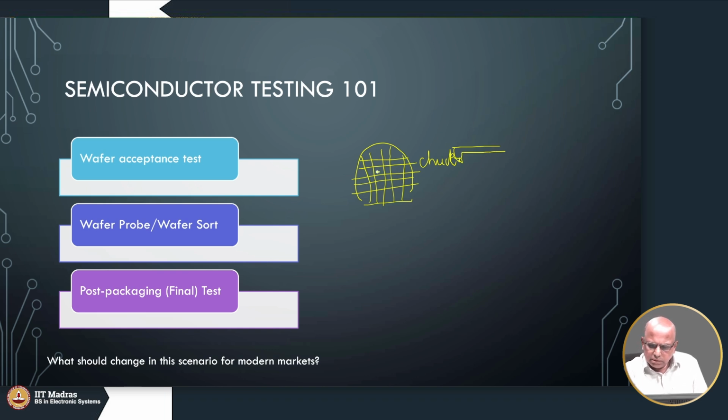So the movement of the wafer, the chuck will possibly not move, it will stay in one place. The wafer will move, and that is done by the robot. And the kind of tests that they do on the wafer are simple tests like are digital pins connected or not. Electrical connectivity.